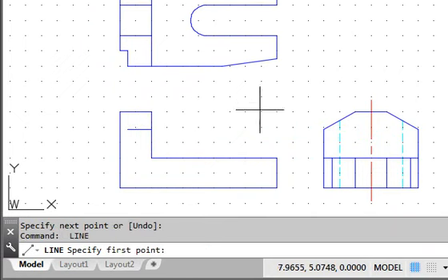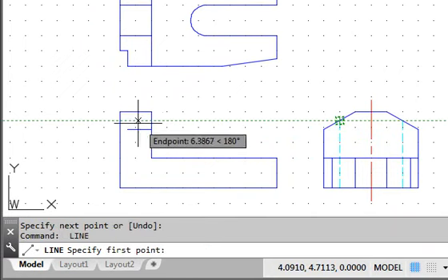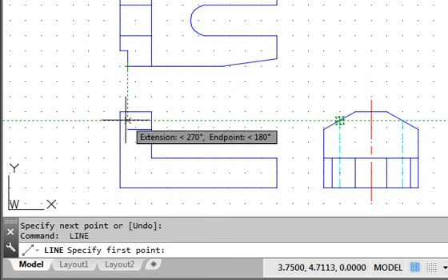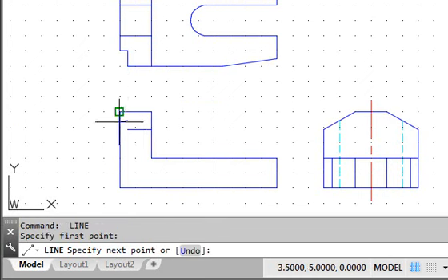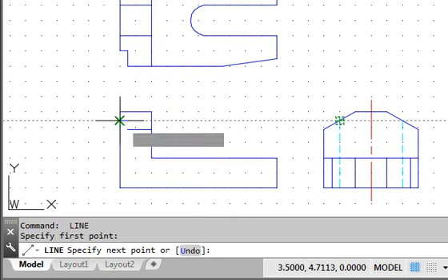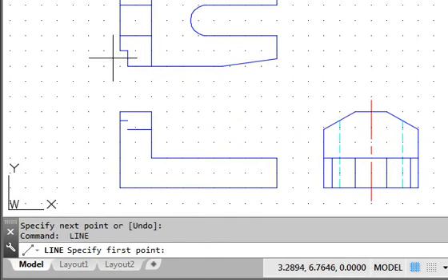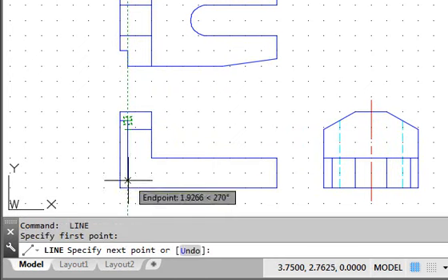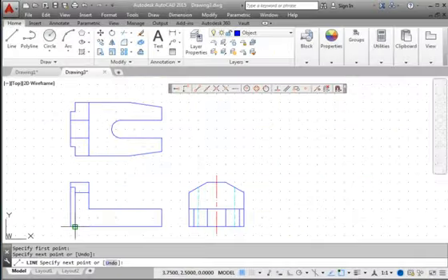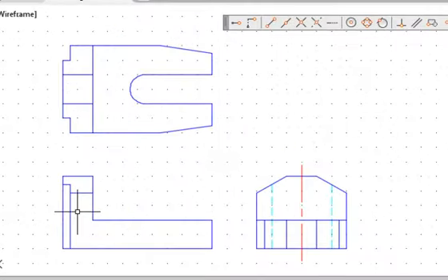We will repeat this process, and this hidden line in the side view represents the corner we need. Tracking the corresponding corner in the top view in both directions, we can create the other horizontal line. We need 2 more vertical lines for the 2 corners from the top view.